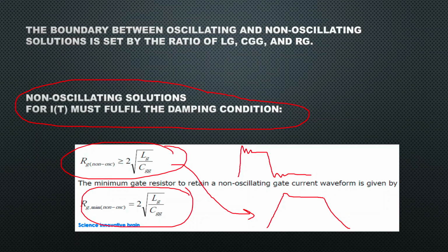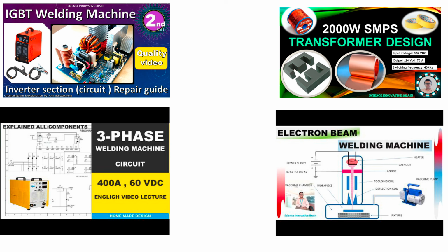With the complementary pulse, if you see here, the dead time is approximately 1 microsecond if you give it. So another pulse will start from here and go like this, and at this point both IGBTs will turn on, the dead time is not followed, and your IGBT will be damaged if it is a half bridge or H bridge configuration. So I hope that with the help of this equation you can find out the correct value of the resistor.